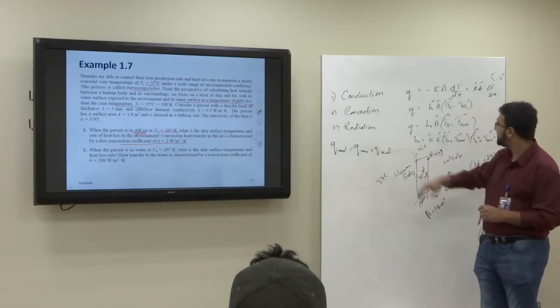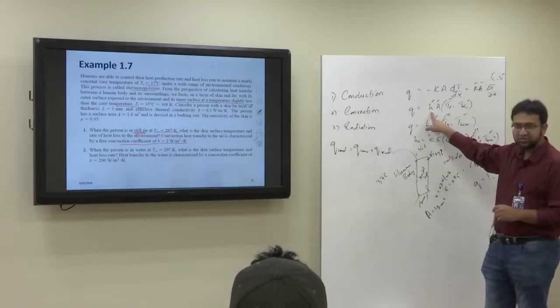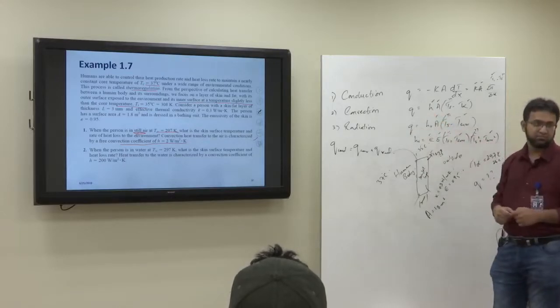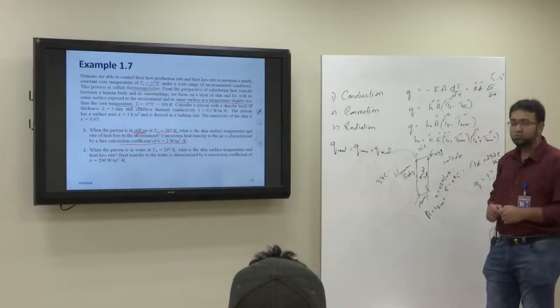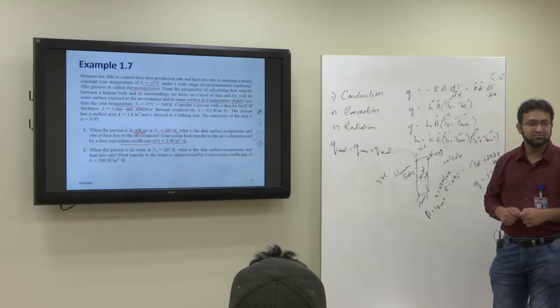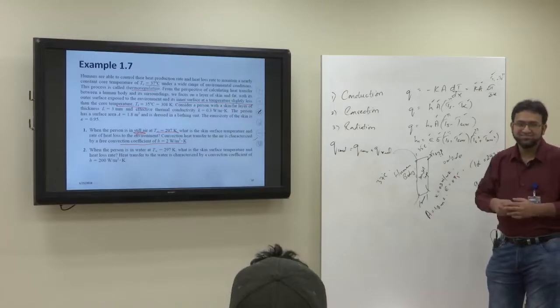Radiation is not there, so this term is not there. h is now different. The temperature of the surrounding would be the same as it's given as the T infinity. Do you need temperature of the surrounding? No, radiation is not there because you are in water.